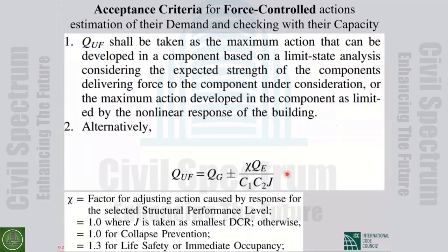In seismic design, why do we put the deformation control parameters, why do we put fuses? Because they get damaged and they don't transmit load to the brittle elements. But the linear analysis can't see that.